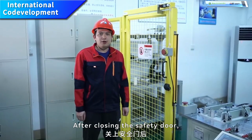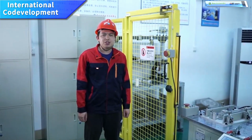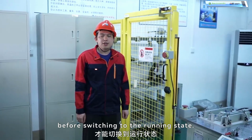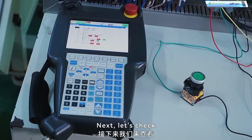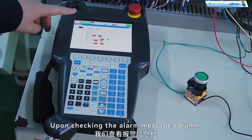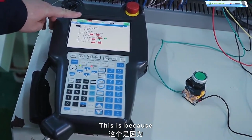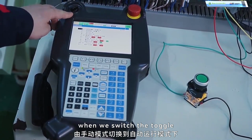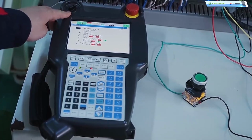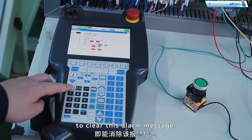After closing the safety door, next, we need to check if there are any alarm messages on the teaching pendant. If there are, we need to clear the alarm before switching to the running state. Upon checking the alarm message column, we find that there is still an alarm message present. This is because a normal alarm message is generated when we switch the toggle from manual mode to automatic operation mode. We only need to press the reset button on the teaching pendant to clear this alarm message.